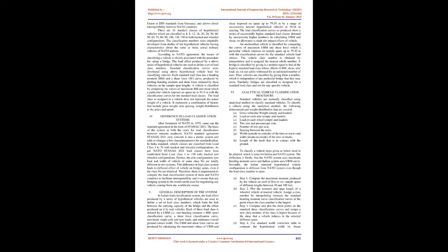According to the NATO agreement, the means of classifying a vehicle is closely associated with the procedure for rating a bridge. The load effect produced by the above series of hypothetical vehicles is used to define a set of load class numbers. Standard classification curves were developed using the above hypothetical vehicle loads for classifying vehicles. Each standard load class has a bending moment, BM, and a shear force, SF, curve, produced by plotting the bending moment and shear force induced by these vehicles on sample span lengths.